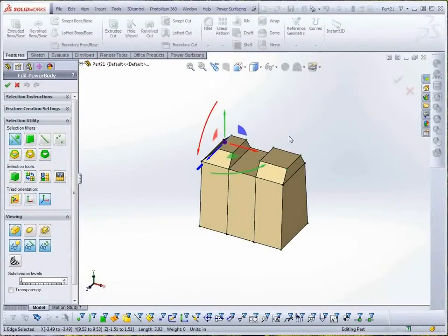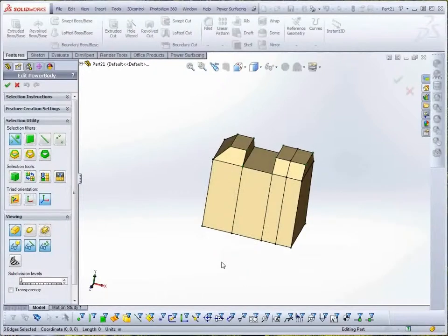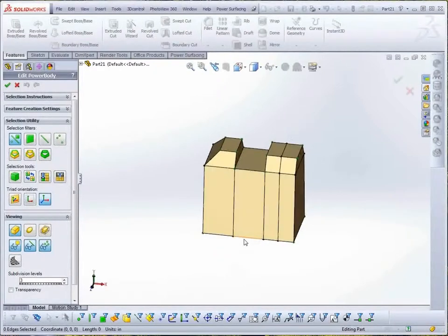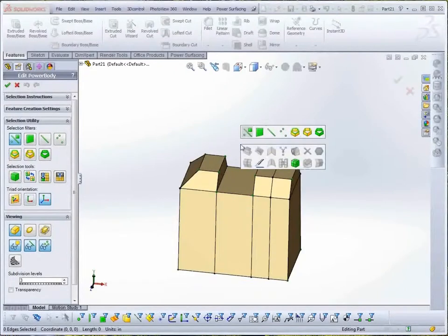I'm going to need one more edge loop at the back. For edges, if I hold the A key down and hover over an edge, I get a preview of the loop to be inserted, and I can click where I want it. It's important to remember that the Sub D edges will not end up where the control mesh edges are, so there's no reason to try to be exact at this stage.